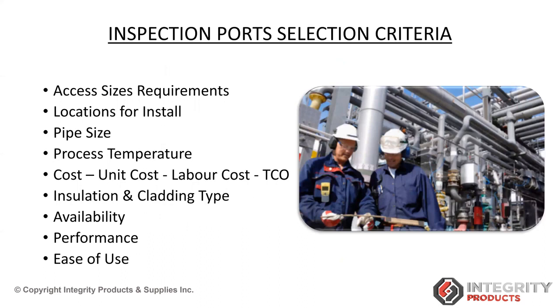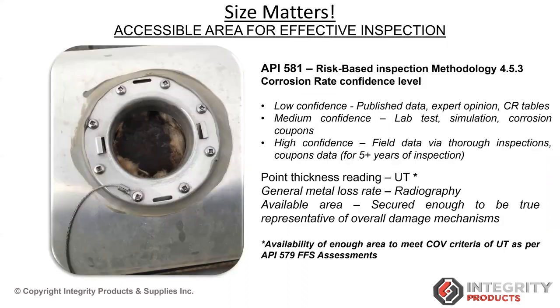Yeah, and here, Ahmad, some of the other questions you may be asking in trying to select the proper inspection port for your application are obviously the access size requirements. Depending on the type of test they're doing, the size of their equipment, how thick the insulation is, access size is one of the big considerations. Absolutely. I would say it's very much decisive on the inspection program. We might come across a situation where we have a CML properly defined, but the size is too small to give you quality data.